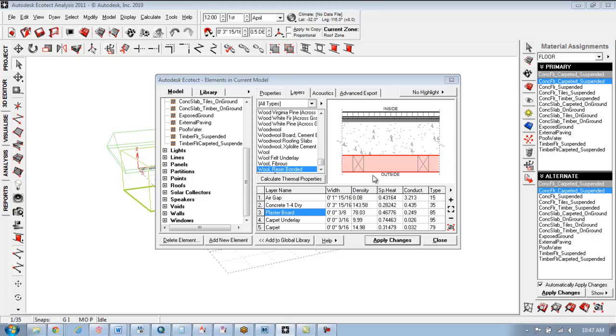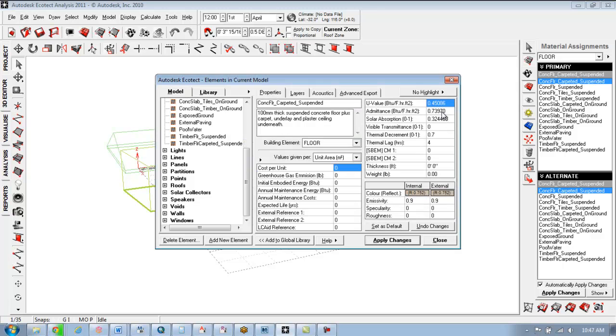Yeah, this is fairly robust in being able to set this up, but like Tuan was saying, it's for your own benefit. If from the initial property screen you just know what the U value is of your whole wall section, just type that in and it'll calculate it the same as if you had actually modeled it correctly on the second tab there. Okay. It's kind of more for your benefit.